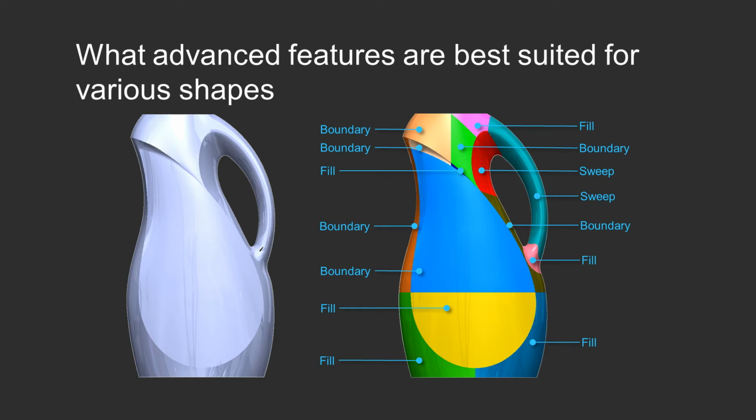You can see that on shapes like these, there really is no direct way to build these as solid models. Sure, you could start with a solid rectangular form and start to cut away at it. But as you cut away, you've got to be very careful that you're maintaining a tangency or even curve continuity with other design elements. So traditionally, the best way to deal with this is to build it from surfaces up into a solid.